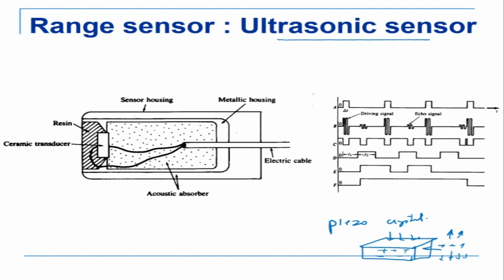Now piezo crystals or quartz crystals are also used in watches. Every time you give it a charge, it vibrates once. That is how the second hand of the watch moves, in watches which are actuated by quartz crystals. These are piezo materials. If you give it a pressure, a charge is produced. If you give it a charge, a pressure is produced, a vibration basically. So this is a ceramic transducer or a piezo.